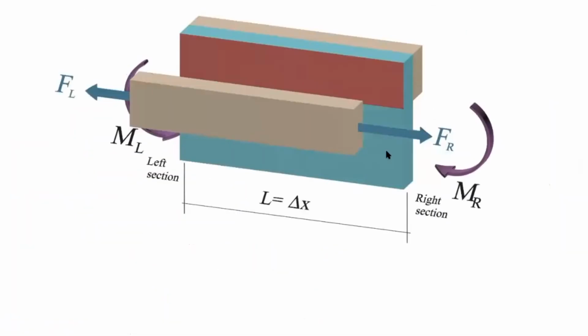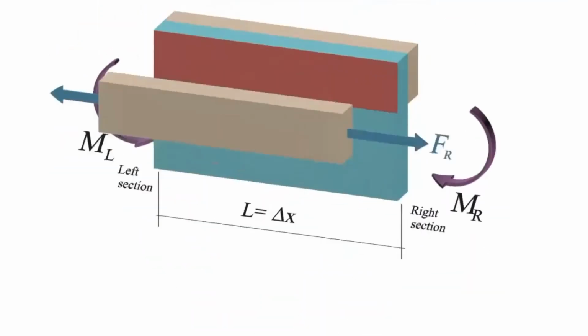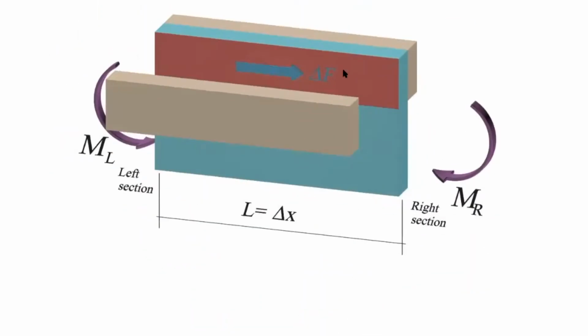In order to calculate the thickness, remember how the shear stress is developed. Shear stress is force divided by area. So force is that balancing force that we just calculated. Remember, balancing force in the unit length is shear flow, or lowercase q, that we just calculated. So if I want to determine how much is shear stress in this problem, how would I determine that? Shear stress is delta F, or balancing force, divided by this red cross-section area.